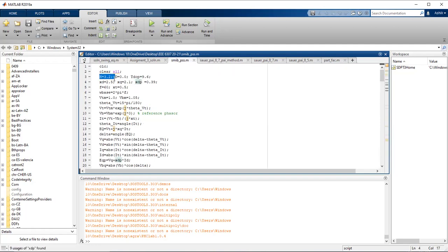So these are the data. You have H, the inertia constant, 3.2, the Td0' is 9.6 seconds, and Xd, Xq, Xd' are not exactly the same as we used before. The data requirement is the same, but the values are probably a little different. Omega base is again 2 pi f. This is the transmission line reactance, this is the base frequency in hertz, and this is the base angular frequency 2 pi f. Okay, now it's a little different.